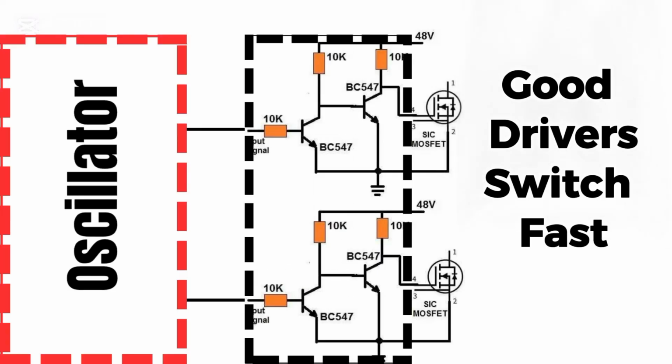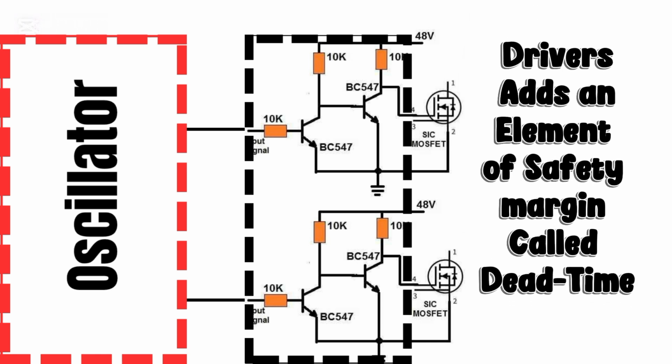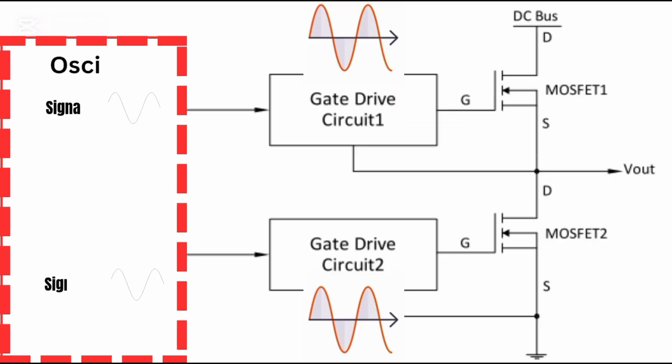Good drivers switch fast. That reduces wasted heat and makes the inverter efficient. They also add a safety margin called dead time so that two switches are never on at the same time, which would cause a short circuit. At this stage, the pulse from the oscillator is made sharp and strong.